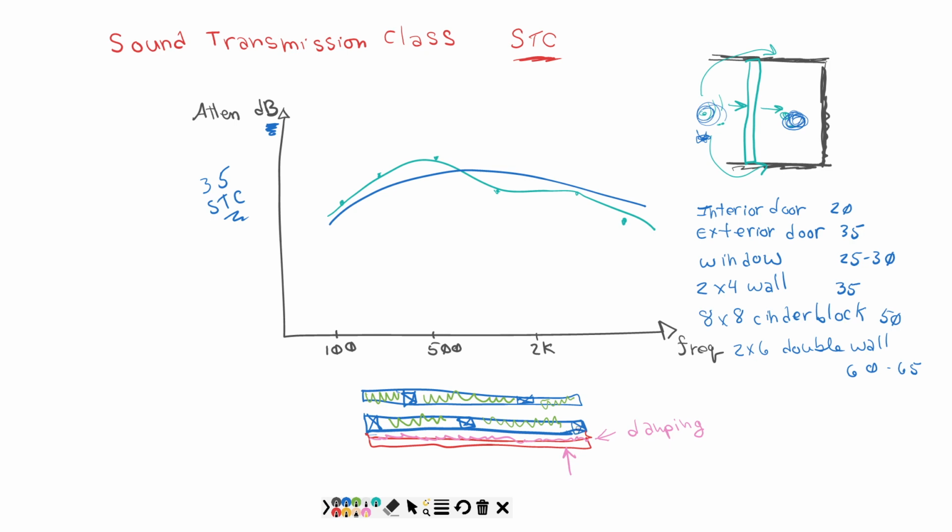So this winds up giving you a fairly thick wall. You have a wall that's at least a foot thick, but you get an STC of 60, 65 out of it. But you have to be really careful. You can ruin this with little gaps and holes and things. If you aren't careful with sealing this, what might seem like an inconsequential little crack or a pinhole is terrible. Just imagine having like a heavyweight plastic bag filled with water. All it takes is one pinhole, and that water is going to come gushing out. All right, that water is going to escape.